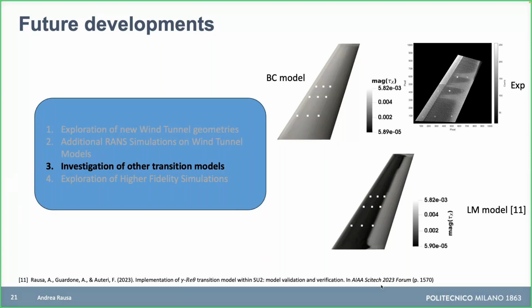For the lifting line instead, you need to compute RANS solutions for the 2D sections of the wing. Since it is an iterative solution, where the lifting line checks the condition for each span section, you have to pre-compute the 2D solutions for a large range of angles of attack, Mach numbers and Reynolds numbers. So it's just a matter of 2D simulations, and then once you have that, you can do all the lifting lines you want for that geometry. But there is this pre-processing step that takes quite some time.